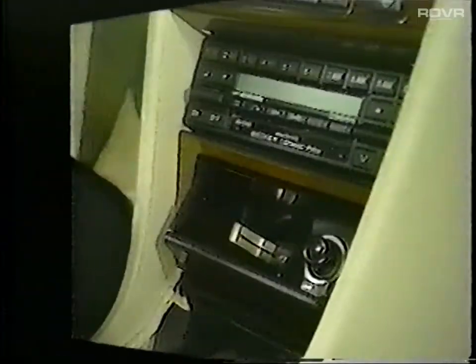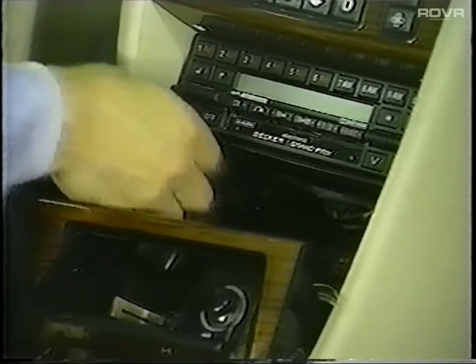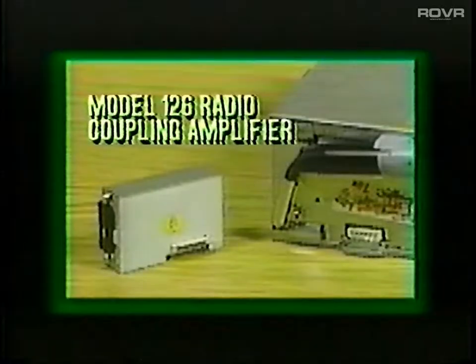The two screws securing the ashtray housing are removed, and the housing is pulled out. The retaining clips for the radio are now accessible. Incidentally, if removing the radio on a Model 126 with the new sound system, you will notice this coupling amplifier. If the radio is going to be exchanged, this amplifier is removed from the old radio and attached to the new unit.